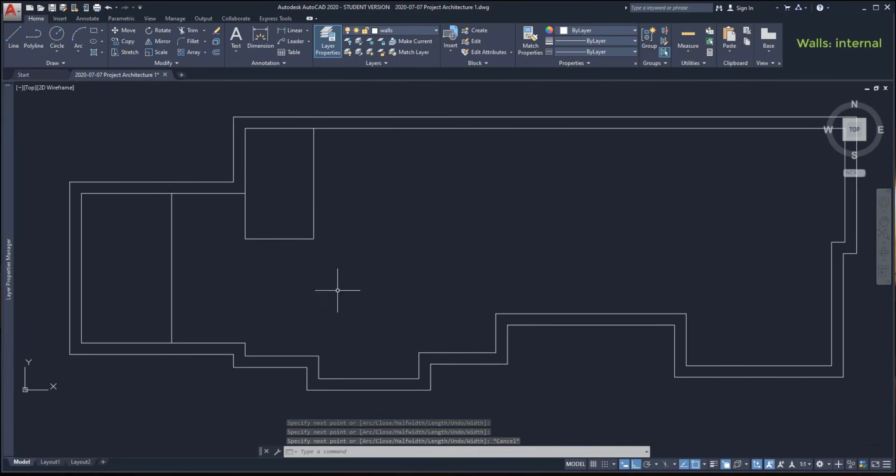After this, I go to the lobby. And I will make this side. From here, I draw 1700 up, then 1400 to the left. And for this line, I need to add the width of the wall to 1650, the distance marked in the PDF. And the total is 1800. That's what I need to type.